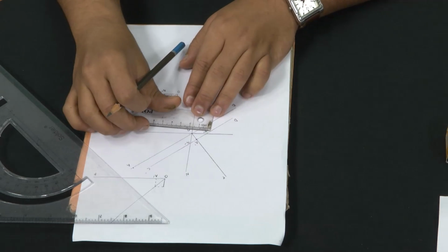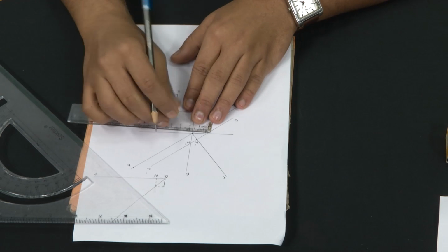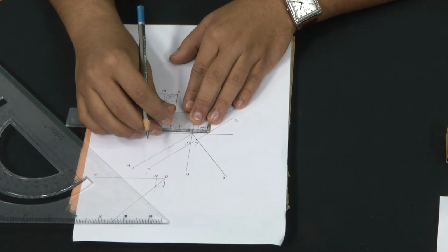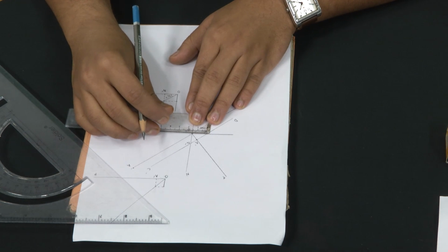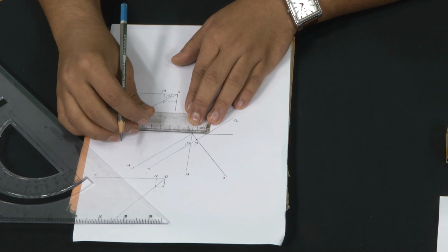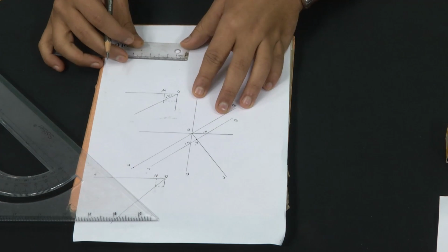In a similar process, we will find out the plunge of any lineation that trends due west. We will first take its horizontal separation or the plane separation to be precise, and then construct a subsidiary diagram.